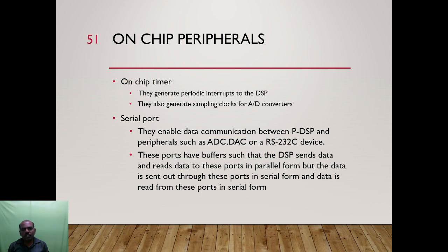Serial port. They enable data communication between programmable digital signal processors and peripherals such as analog to digital converter, digital to analog converter, or RS-232. These ports have buffers such that the DSP sends and reads the data to these ports in parallel form, but the data is sent out through these ports in serial form and data is read from these ports in serial form.